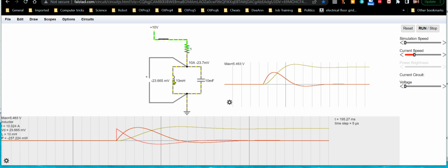Whereas this data, as I said in the first part of the video, comes from this meter here, and this little current probe here. But this is directly what's going on in the components themselves. That's why drawing them properly is important, like I discussed in the first part of the video. But the quiescent state is that you end up with a current constantly flowing through the inductor, which maintains the energy it has stored in its magnetic field.